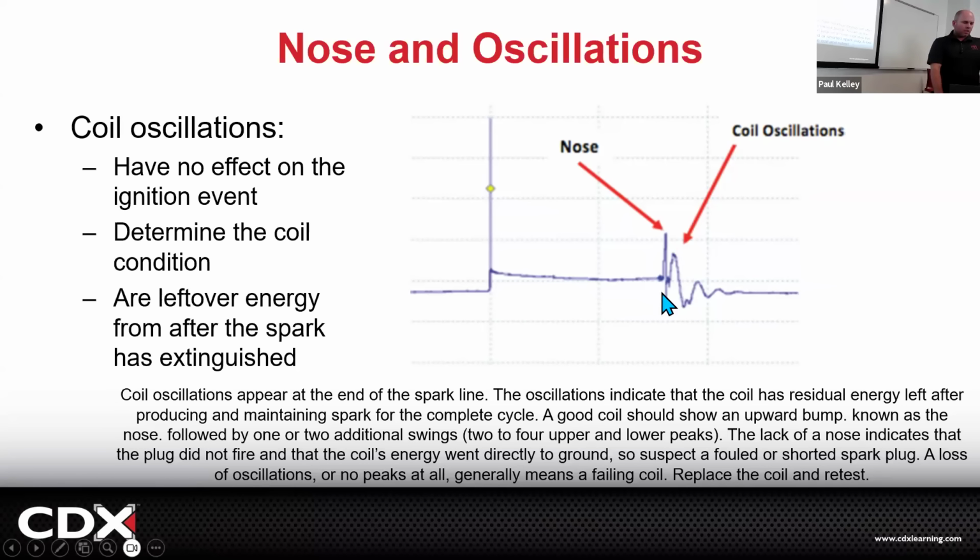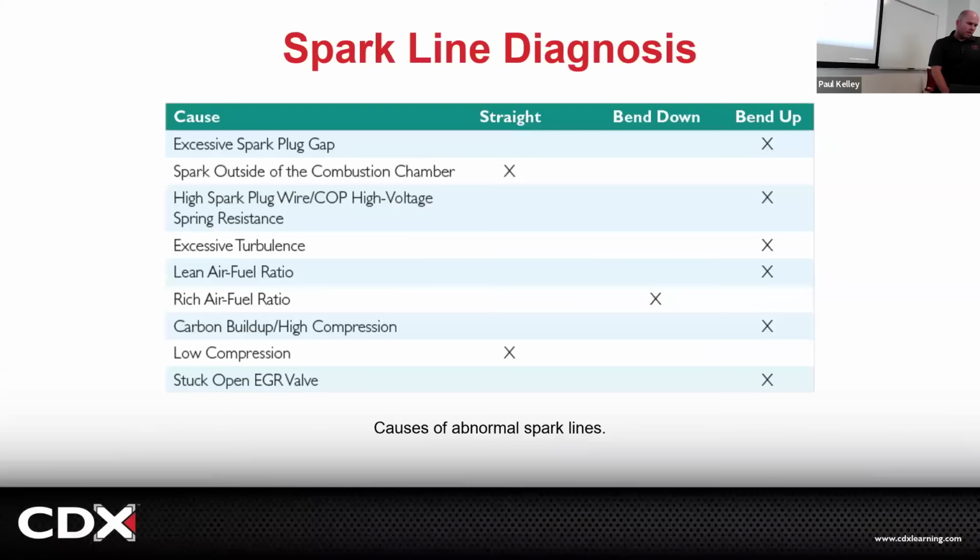What the oscillations are, that's basically the coil's voltage going up and down as it's been discharged and it's kind of stabilizing. It's spent right here. By the time you see the oscillations, it's got a little bit of energy. If it was dead flat, it'd be empty, but that means the burn time is over. We're done. And it should have a little bit of an uptick like it does if it's got some energy left in the coil. Okay, so there's a bit of leftover energy there.